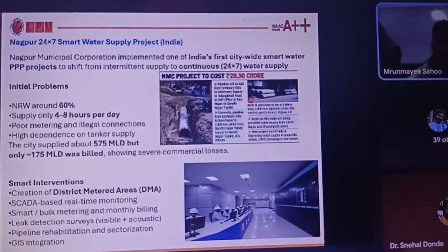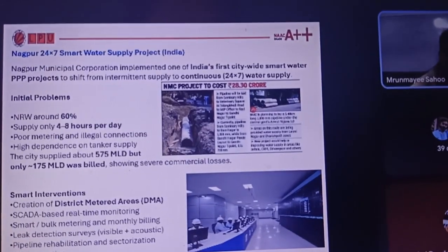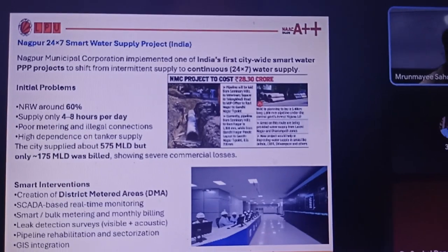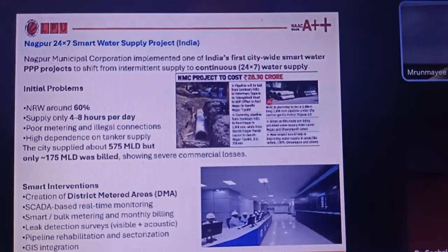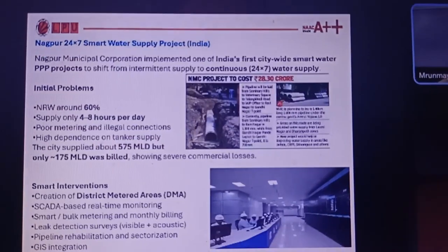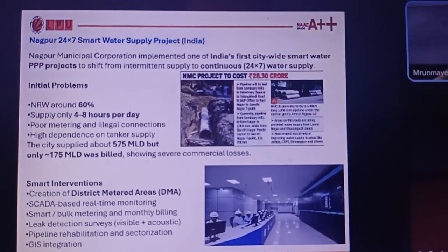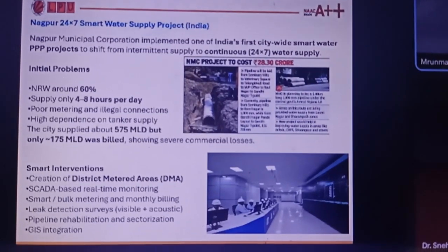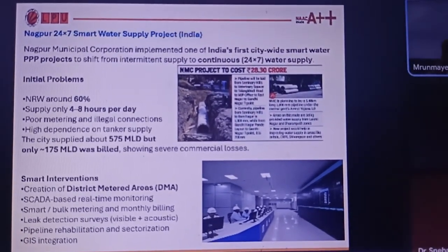We are taking the water from the same reservoir, the reservoir which is supplying other areas also. So right now, it was again reduced from 4 to 8 hours to 24/7. So we are supplying 24/7 water, and the demand is being managed. The demand again will be given by you as input. We will say 135 liters per capita per day we are going to supply.